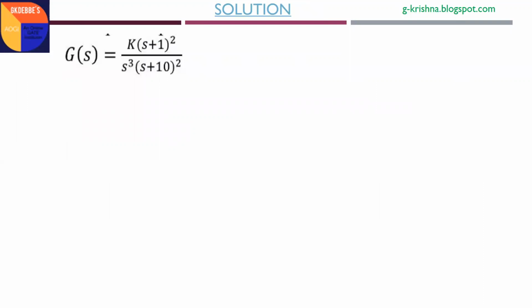So this is the open loop transfer function. We explored these things in the previous topics also, in the root locus technique. Everywhere we have discussed these concepts, but we didn't give the numerical data. Already we explained the concept of lead systems connected with the 3 poles lying at the origin, and how the phase plot of this system looks. Since there are 3 poles at the origin, we have the starting angle as minus 270 degrees.